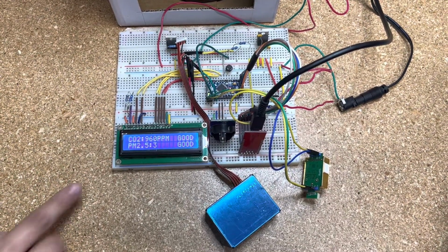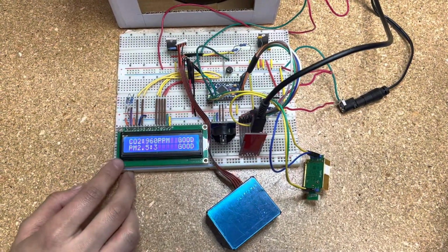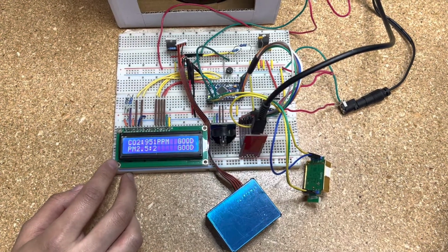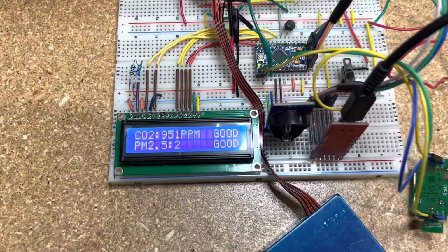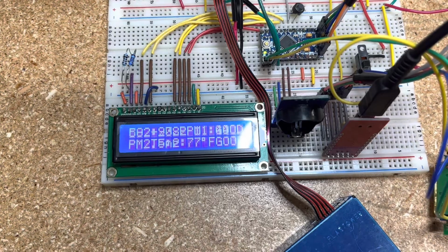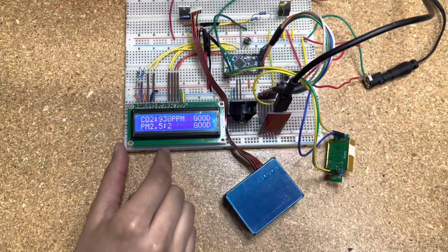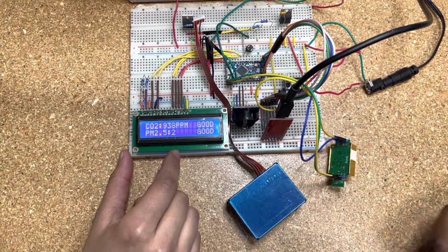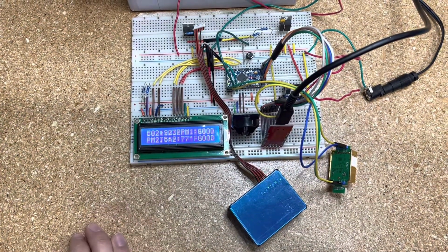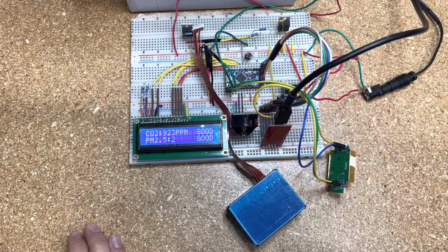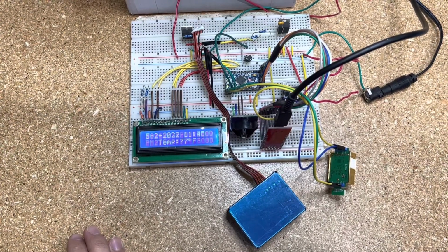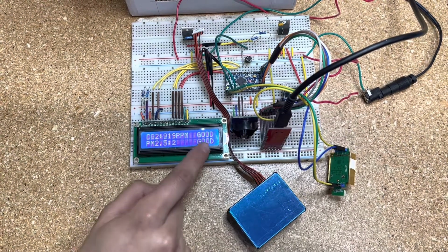This first screen switches display between the current date, time, and room temperature, followed by the current display of the carbon dioxide sensor values in parts per million units, and the particulate matter with diameter of 2.5 microns or less sensor values in micrograms per meter cubed units. The sensor screen also provides a qualitative indicator of the status of the sensor value readings as good or bad.